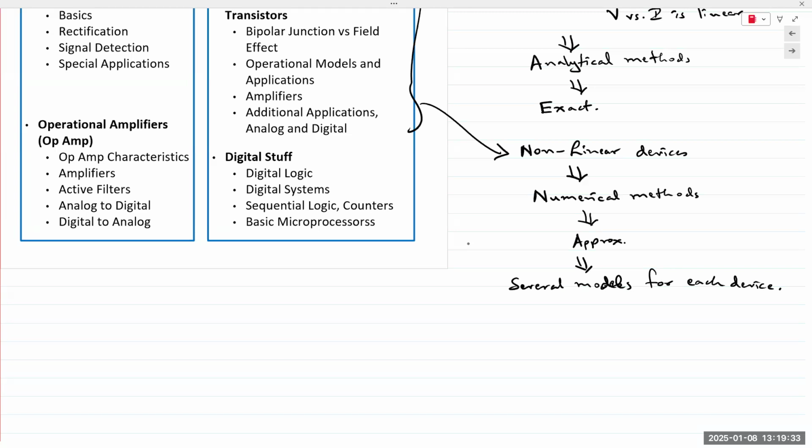So then next I might assume that the value is between 0.7 and 0.9. And now if I get 1.1 volts, then I'm above that range. So I'm going to make a third assumption. And I would keep doing that until it fits. Okay, that approach is known as an iterative analysis. So you keep plugging away until you arrive at an acceptable value.